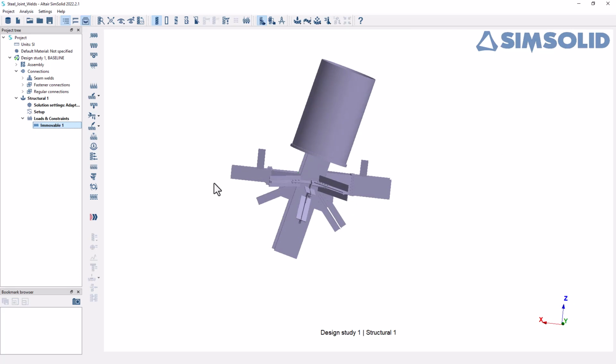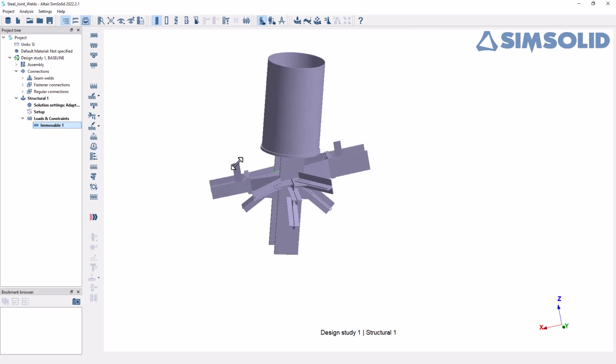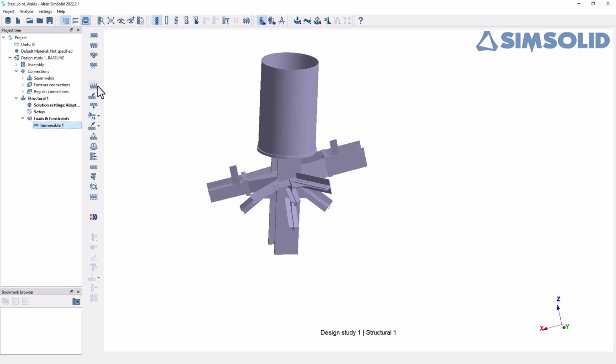And another item that I want to represent is my loading conditions. As you can see here, we have a number of different loads that we can apply to the model, and some of them may not necessarily all be relevant to our applications. I could obviously apply a pressure load or a specific force or displacement. So for example, if I knew that this beam was deflecting 2 millimeters downwards, I could apply that type of load and observe the resulting forces in the rest of the model.